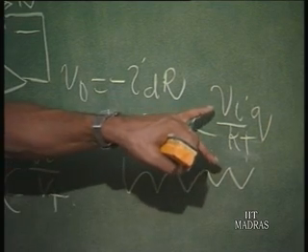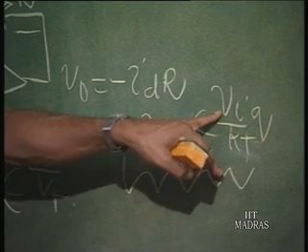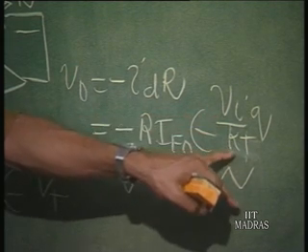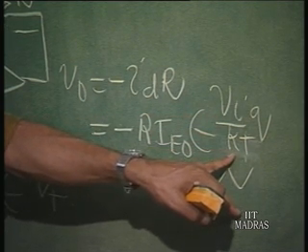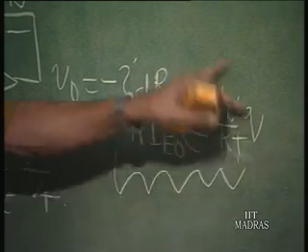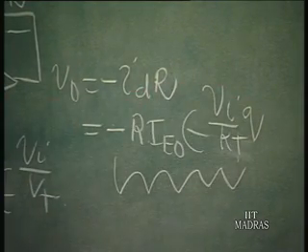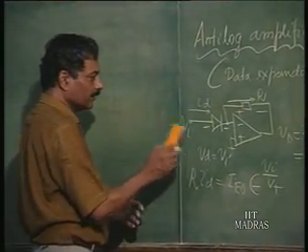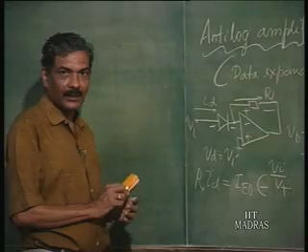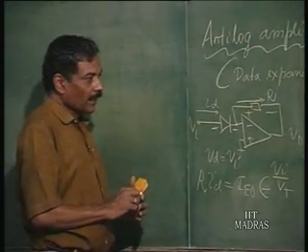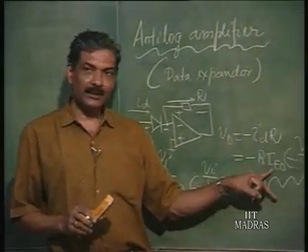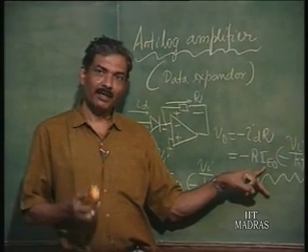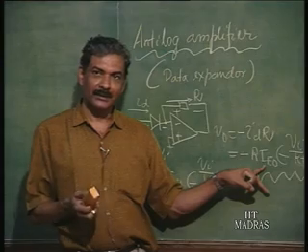It is very simple. If I now introduce an attenuator here and make it alpha and design that attenuator network to compensate for KT over Q, that will take care of the temperature variation of this, right. So, it is necessary that I put an alpha network for this particular thing, that is you put an attenuator here, okay, and IE naught has to be compensated for in a similar fashion, okay, by developing a voltage and then subtracting that